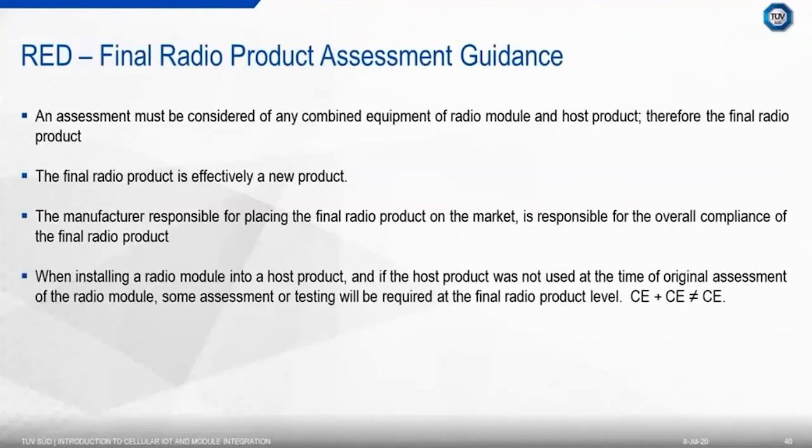Any combination of host and radio module effectively becomes a new product, and this new final radio product should be assessed to the essential requirements of the RED. The manufacturer placing the final radio product on the market is responsible for the overall compliance of the final radio product. Some form of assessment will be required on the final radio product which incorporates the radio module if the host wasn't used at the time of the radio module assessment.